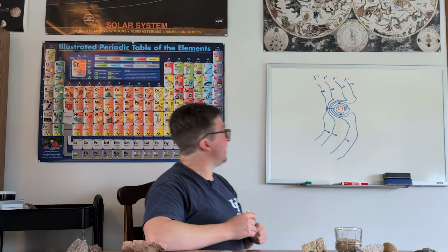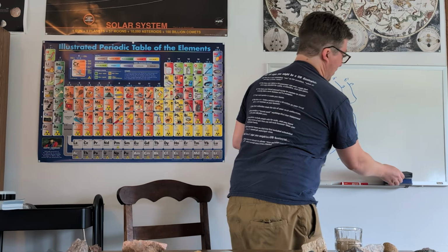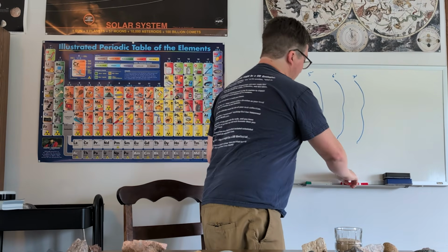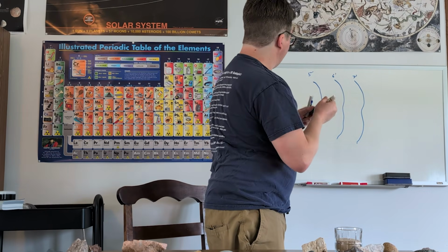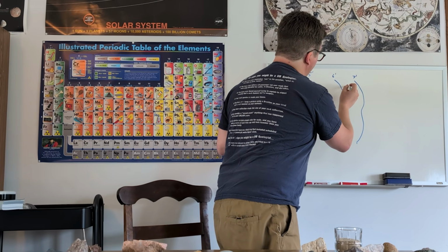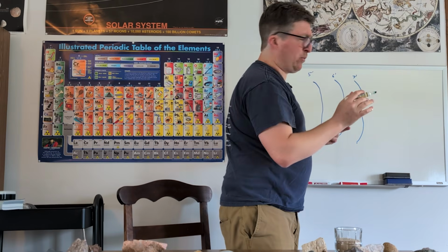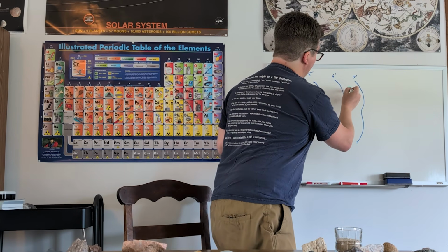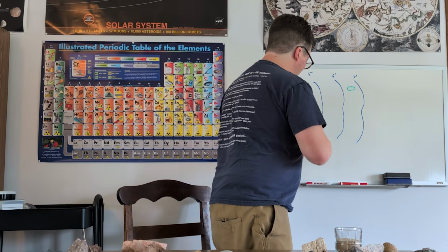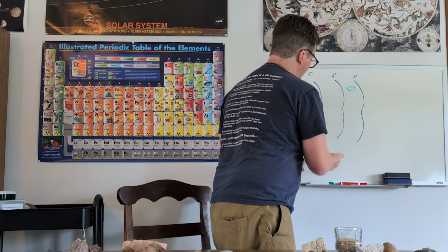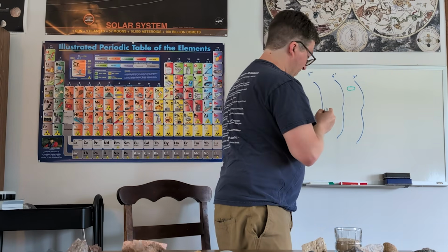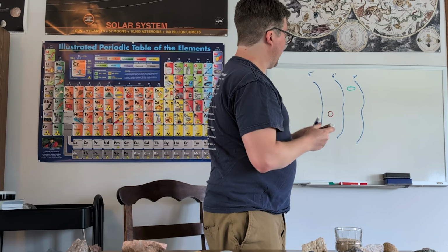It may not be a coincidence that your water smells like crap. Well, why is that? Well, because you might have a situation where your septic tank has been placed, and I'll make it green. I'll say your septic tank is right here. Let's say they put it in responsibly, and they put it in over here where the groundwater is lower, and your well has been put in right here where the groundwater is higher.